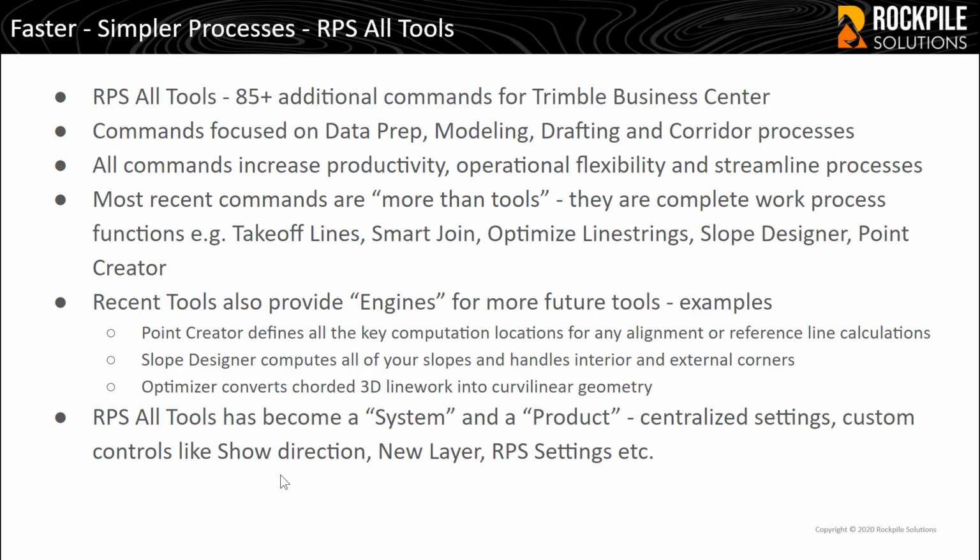For example, our Takeoff lines command allows you to digitize any type of line. Digitize using CAD functionality or digitizing over the top of PDF files. Takeoff lines allows you to create 2D lines for contours and building pads, 3D lines for curb and gutter, sidewalk, and other features on the job site.